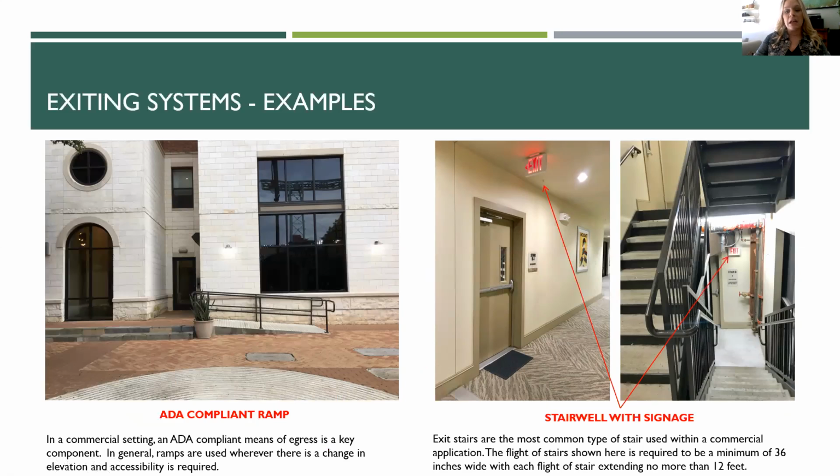It's required to be a minimum of 36 inches wide, and each flight of stairs extending no more than 12 feet, which is shown here as well. Again, additional signage, this is going to be denoting where you are in the building and where you're going to be traveling to once you exit into this exit access stairwell.